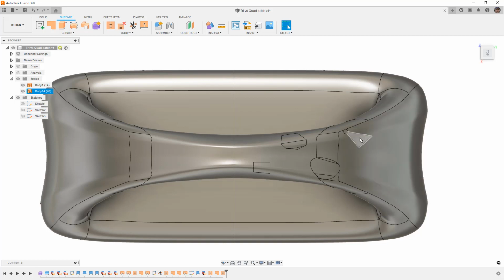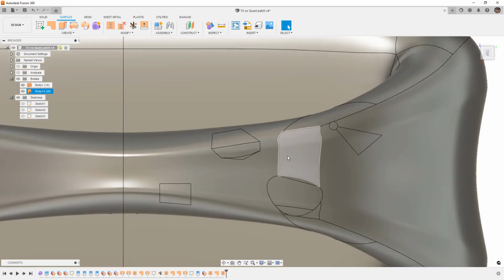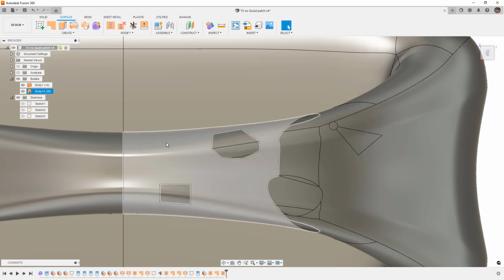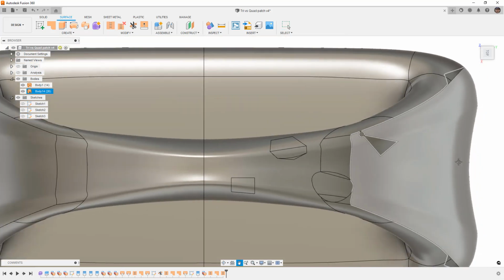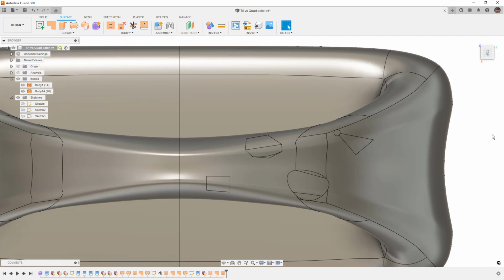Do I have geometry? So for example, this section here, I could have pulled from this section. This section here, I could have pulled from here, and so on. If it has symmetry, in this case, across the YZ plane, do I already have a section of surface that I can use and build in to it? If any of those are true, then use what you have to build in the surfaces. If they're not true, then obviously you have to work with what you have.